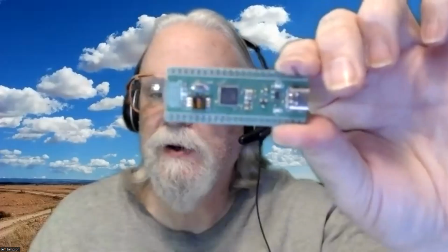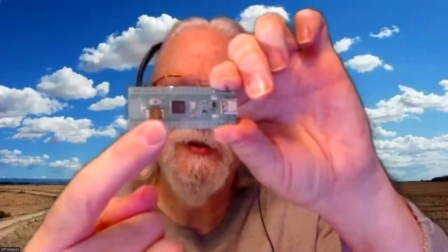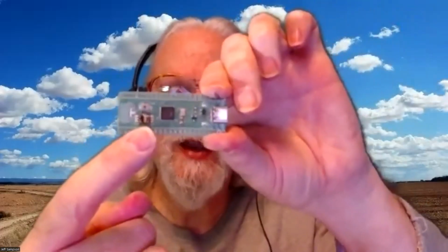So it's got this crappy little dip switch on here. It's a 3-position dip switch, just little microscopic switches on it. Right now it's covered up with tape. You have to take the tape off. So what you have to do is move one of the switches to a different position and press the reset button. And then the board comes up in this DFU mode. So as long as you have something that talks to DFU, then you can go ahead and program that.